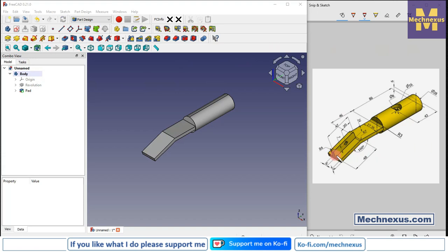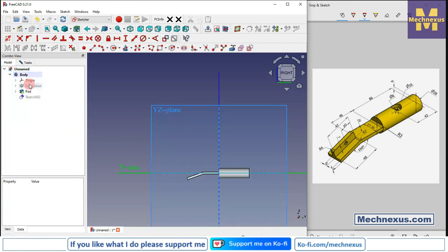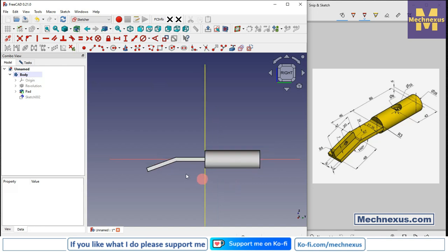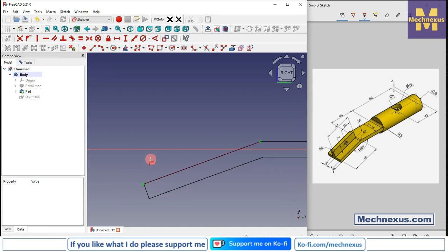Now we will add this plate here. So we will turn on our origin plane again and select this mid plane and click on the sketch. And now the first thing we will do is to project this edge, and we will switch to the wireframe for better visibility. And now we will create a line equal to our projected line.